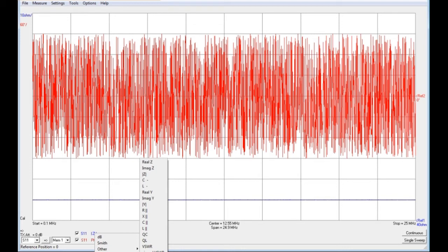So I measured S11, and the calibration that I've now applied allows this software to show the output in many different forms. And that's a very valuable thing to be able to do. It's handled inside the software. I don't have to be concerned about that, but I just do need to check at the beginning before I take unknown measurements, and at the end, that my calibration is correct, because the parameters that I'm reading off here are dependent upon the quality of that calibration.